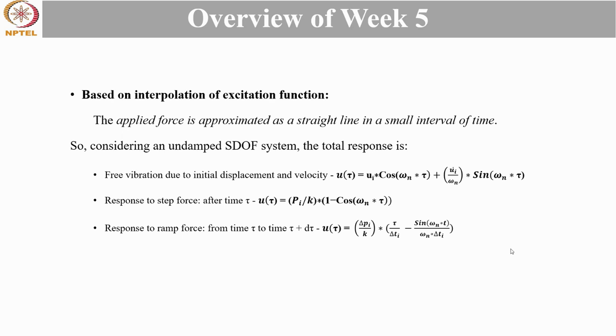So the first one is based on interpolation of excitation function. In this method, the applied force is approximated as a straight line in a small time interval. So considering an undamped single degree of freedom system, the total response then will be due to three parts: due to initial free vibration, due to the impulse created by the step force, and due to the ramp force between two small time intervals, as we are considering force as a straight line.